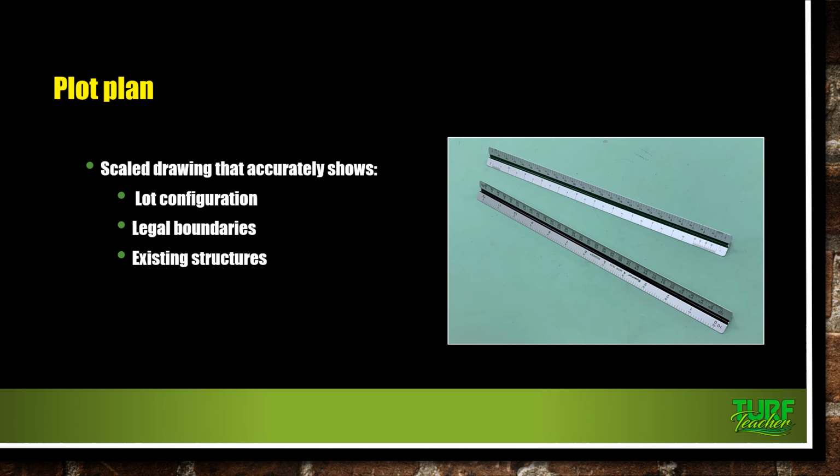But typically what we do our designs with in irrigation and landscape is on the quarter scale, 1/4 inch equals a foot, or 1/8 inch equals a foot, and that's on the architect scale. If we're using an engineer scale, it's going to be 1 inch equals 10 feet, or 1 inch equals 20 feet. But nice set of scales there, the aluminum scales.